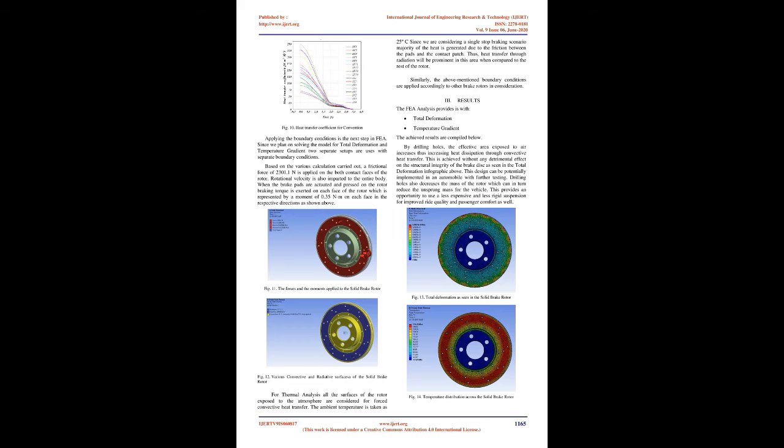KE equals 777,622.33 joules. Deceleration of the vehicle equals 6.86 m/s². Time taken to stop the vehicle equals 4.853 sec. Total stopping distance equals 131.03 m. Reaction time equals 1.5 s.